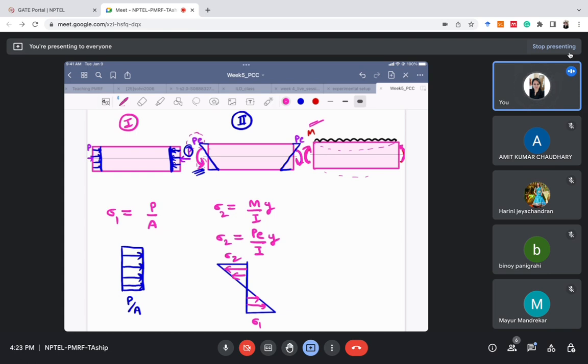the tension, right? And the stress will be bending stress, because bending moment is applied, so bending stress will be there, and the magnitude will be M by I into y. But here the M will be due to this UDL. So the magnitude is M by I into y, and if I want to draw the profile, the top part will be under compression and the bottom part will be under tension. So this is the kind of profile if I want to draw the tension and compression. Are there any doubts till now? Any doubts? Okay, so this is the thing.